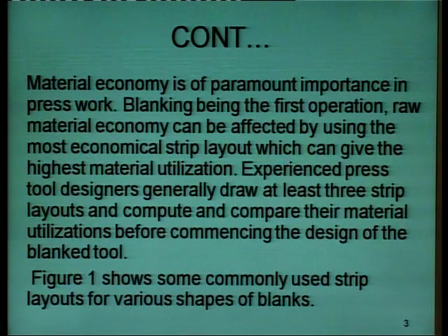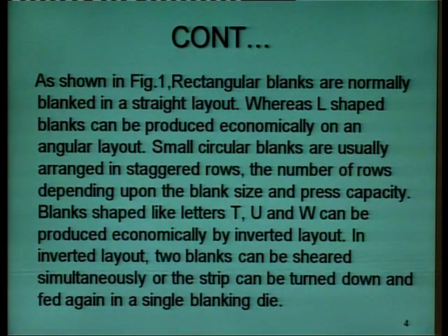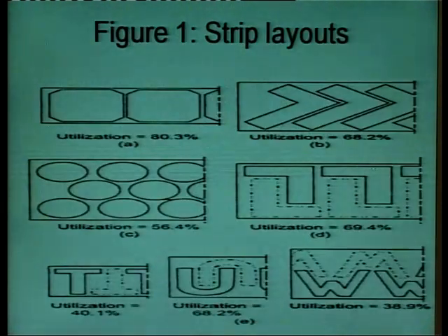Now, what do experienced press tool designers do? They draw at least 3 strip layouts, then compare their material utilizations before coming to the final design of the blanking tool. Now, I will show you the figure which tells us the various shapes of the blanks. As shown in figure 1, in this there are various designs of the layouts. So, we will study them one by one.